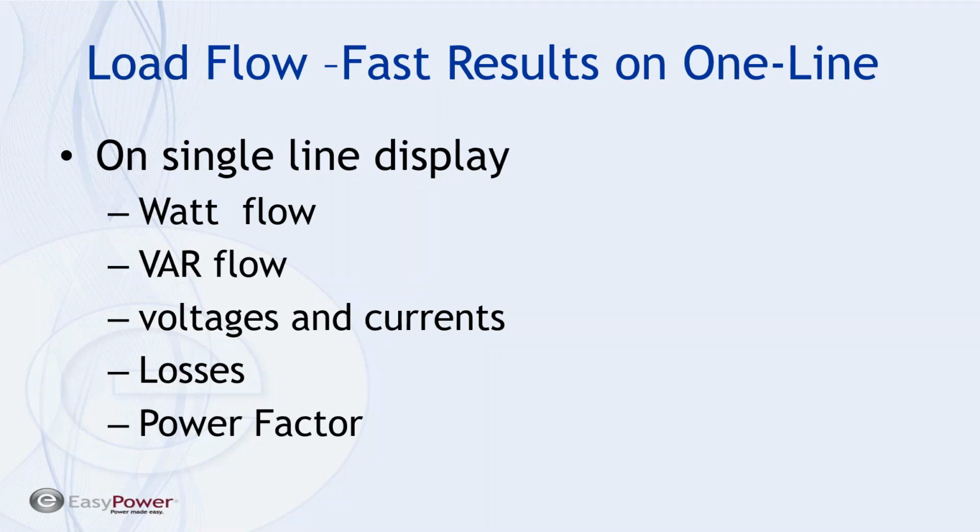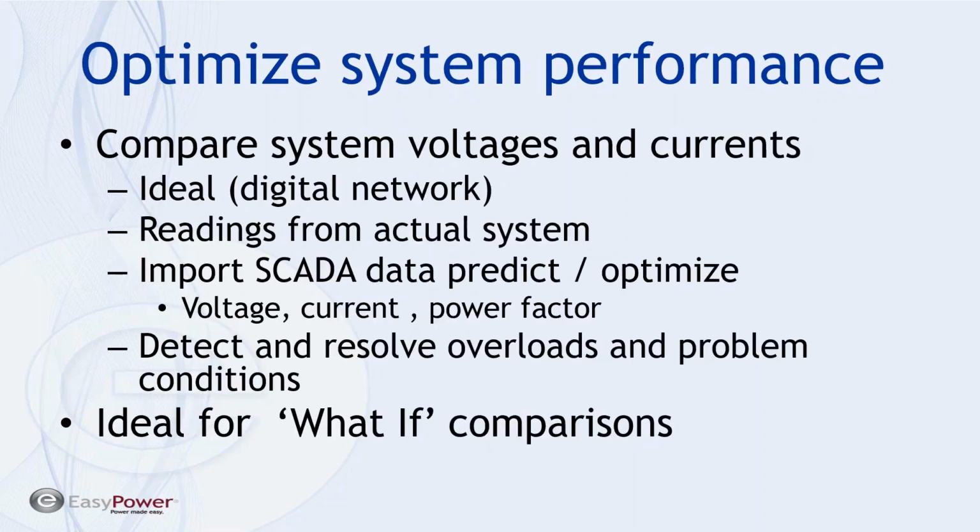And one of the elements that we want to stay on top of, frankly, usually in areas where there's a penalty from a utility company if we don't maintain a certain power factor, is to stay current on what's going on with our power factor and optimize on that result.